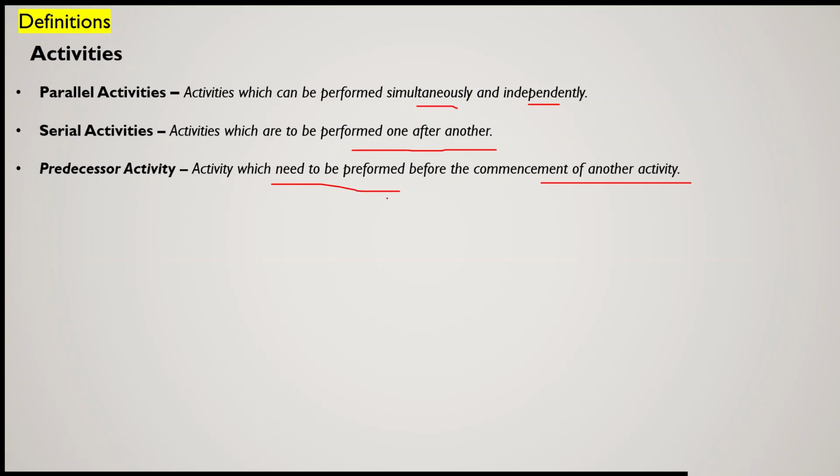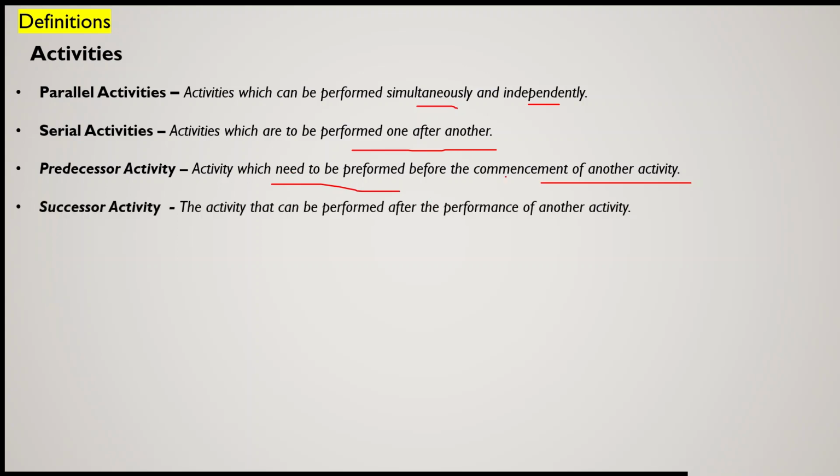As excavation of the foundation is one activity, that will be the predecessor activity to the other activity, that is laying of PCC, because laying of PCC can only happen after the excavation of the foundation. So excavation of foundation will be the predecessor activity, and laying of the PCC will be the successor activity, because it will succeed the excavation of the foundation. So, an activity that can be performed after the performance of another activity.